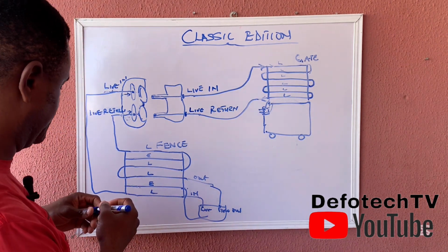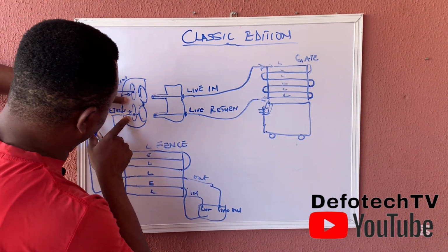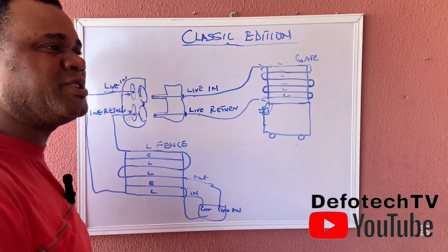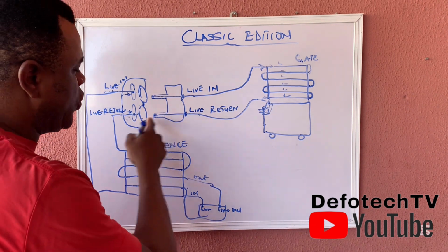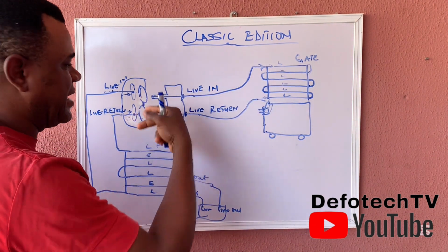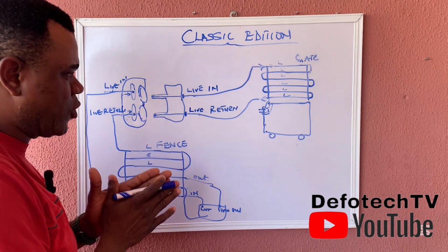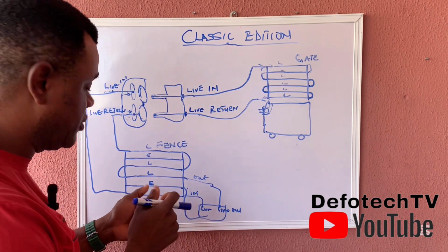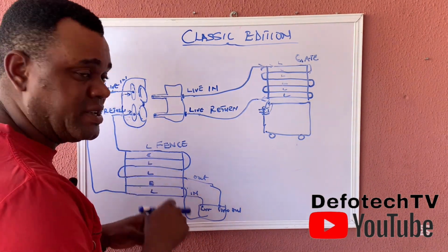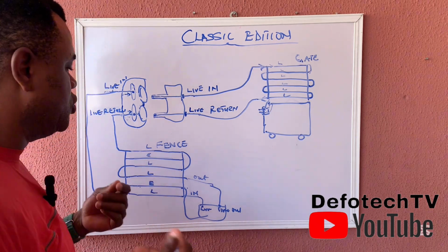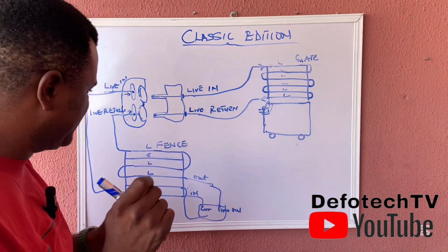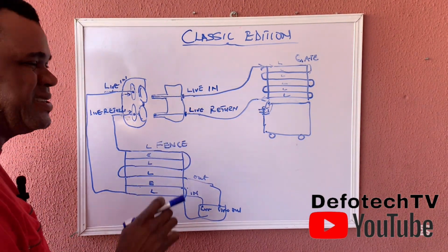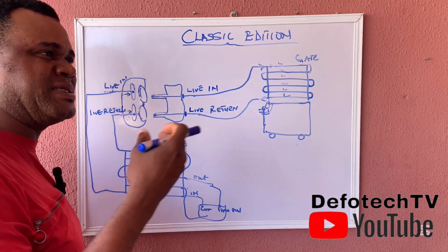Like I said earlier, only when this thing pushes the foot to this place, that's when it closes this. That's why your fence would not raise an alarm when the gate comes in, because those few split seconds are not enough to trigger an energizer. Have you ever noticed when you carry your lines trying to breach your energizer to trigger the alarm, maybe the live and the neutral, if you just touch for a second or two, it doesn't go off immediately? So there's a delay to actually sense, is this actually a fault?